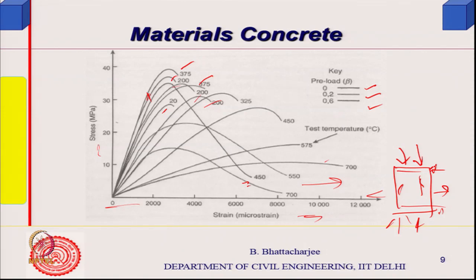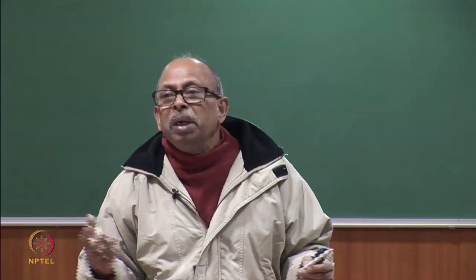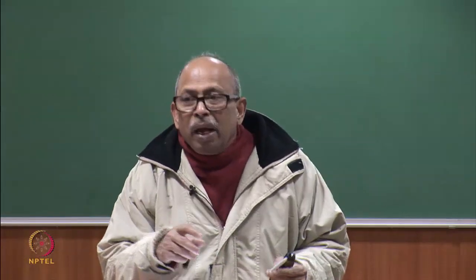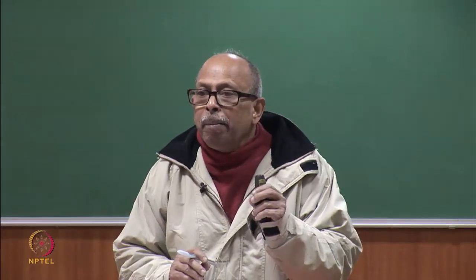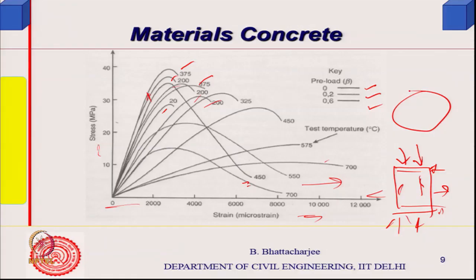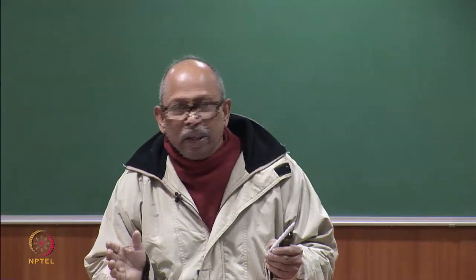So, when you raise it to 700 degrees centigrade, there has already been expansion in all directions, right. And the failure now has to start from one of those cracks or whatever has formed. Total deformation, if you look at it, you will find much larger, but the load it can carry is much less, because cracks are already there. And if you recollect, or may not have studied, actually the strength is governed by the weakest link. So, you have cracks already existing in the system, and fracture will initiate from those cracks, largest cracks in fact.